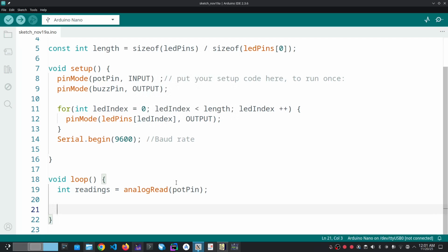In ADC conversion, when you have the ADC at 10 bit, that means it's 2 raised to power 10. That is 1024, starting from 0. That will be our readings will start from 0 to 1023 to make up 1024 bits.